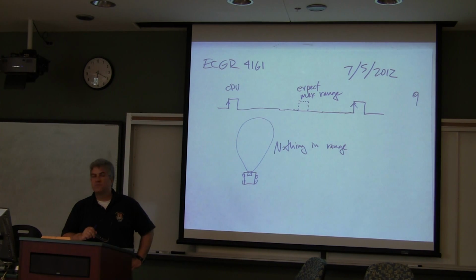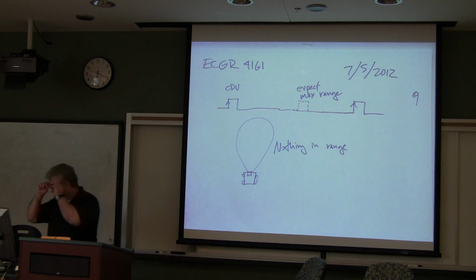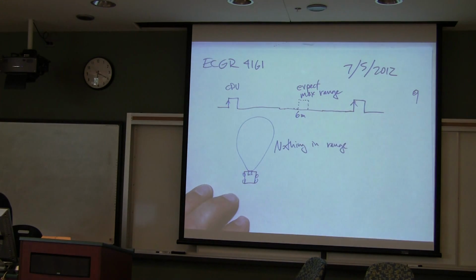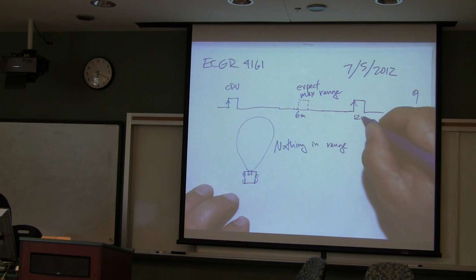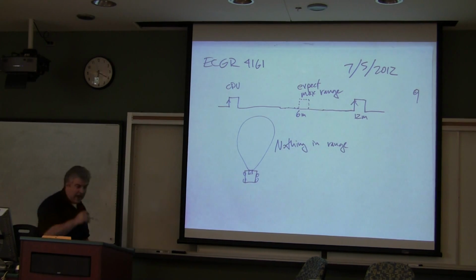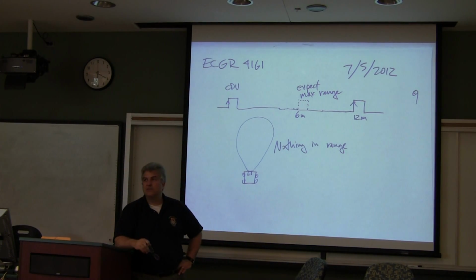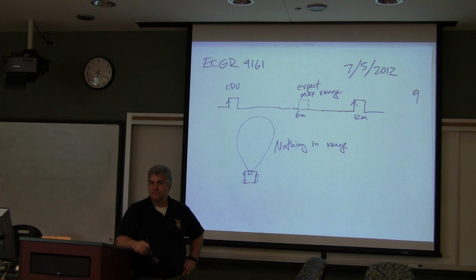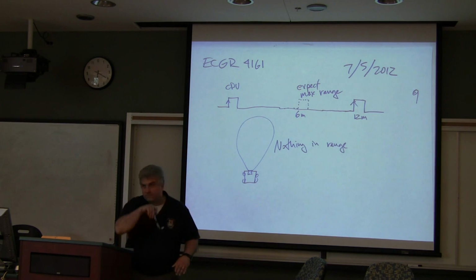So in this case, if the sensor would recognize 6 meters, maybe this is the time that would be equivalent to 12 meters, and your software has to be smart enough to know not to accept that as a distance, because it goes way beyond what the range is of that ultrasonic device. In other words, you have to write smart code. Shouldn't be that hard.